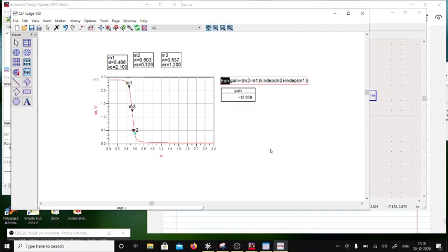So let's express this in dB. This would be the gain in dB, and I forget about the sign. The phase shift is 180 degrees, so I will put a minus sign here, and then I do 20 log of this. So it will be 20 times log 10 of this number.